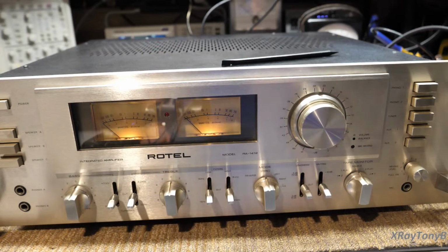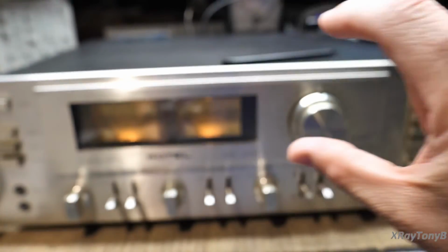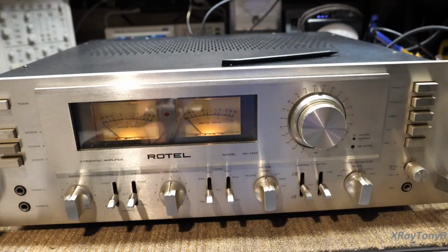Alright, now if you recall on many of my other videos that I did in the past, I would do a frequency sweep, right? Where you would start at 20 Hertz and you'd sweep up to 20 kilohertz, and you would monitor the speaker output, and you would make sure that the amplitude doesn't shrink or grow during that frequency sweep. So checking for linearity in an amplifier, you really don't need a frequency analysis program to do that.